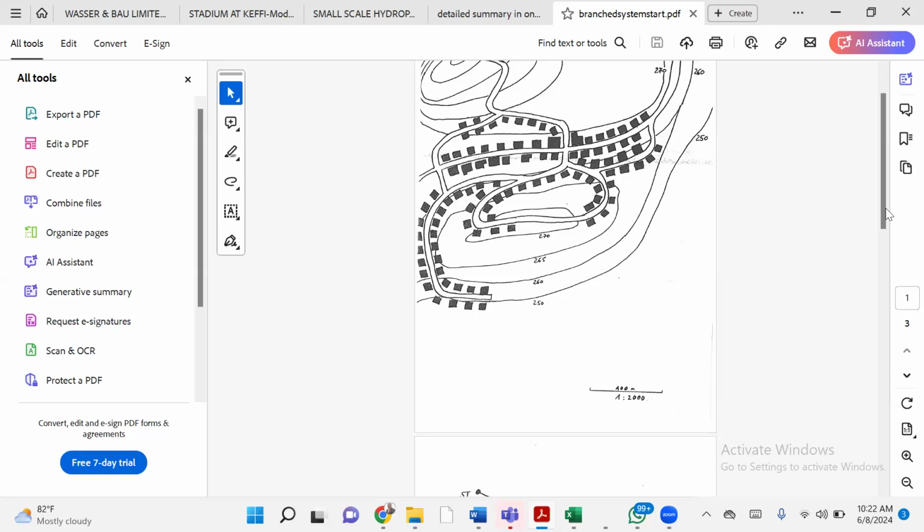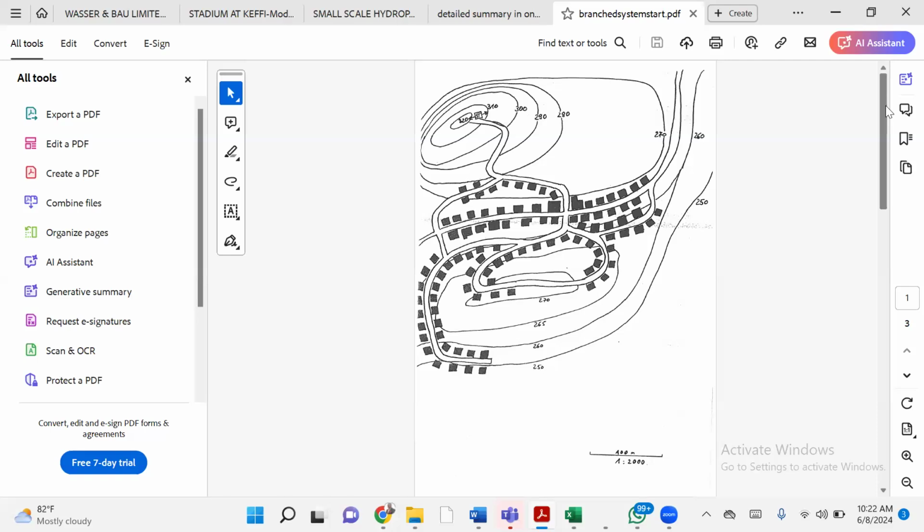Now, it means that if you need to identify the lowest point, you need to identify the highest point. Why do you do that? Because water will flow from the highest point to the lowest point, and there's no pressure, there's no pumping in the system. So if you come to a community, you take your spot height, you know where the lowest buildings are and where the highest building is. Your elevated tank is going to be located at your highest point. And of course, most likely, your water source is going to be located at the river, the lowest point, groundwater.